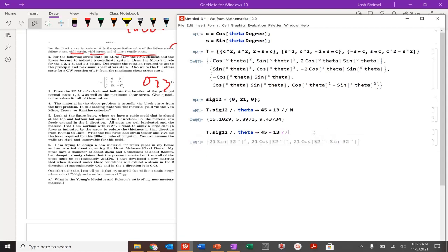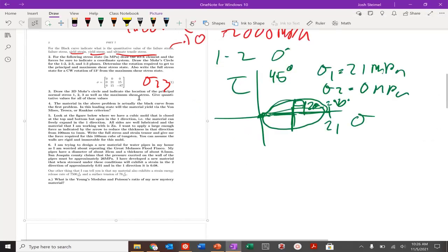I can look at this numerically as well. So you see all I'm doing is flipping here. We still have the same values. So these are equivalent stress states. I could also look at basically the max shear and rotate that way, but you'll see the values are exactly the same. So we got it. So first plane is done. What about the next plane, the 2, 3?